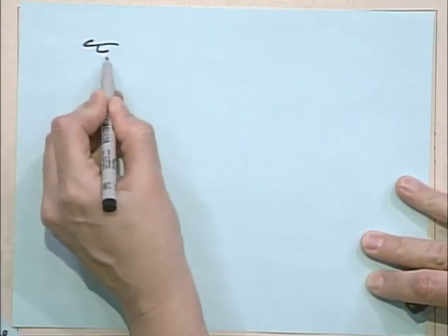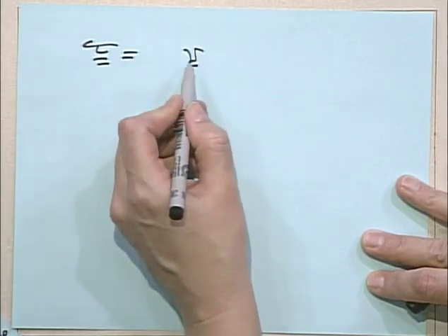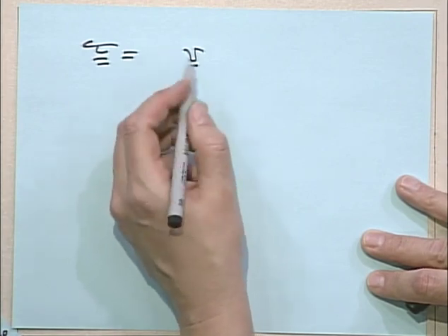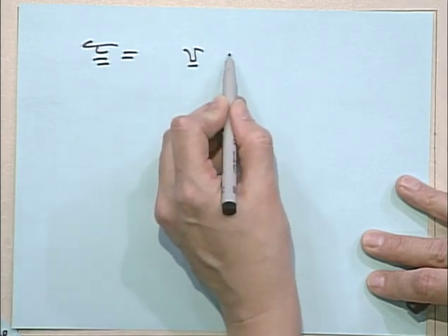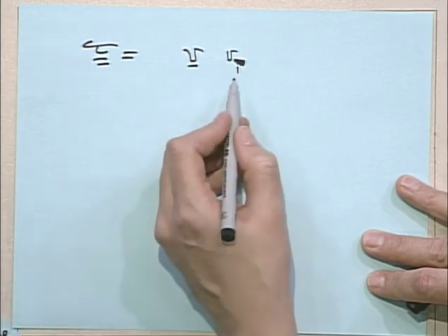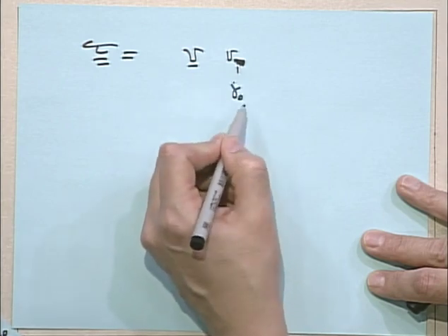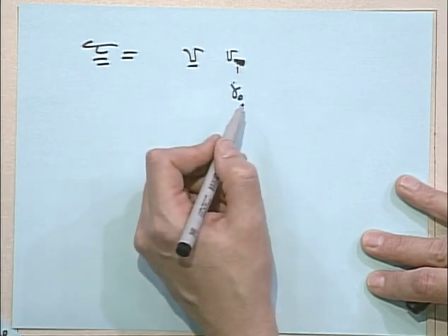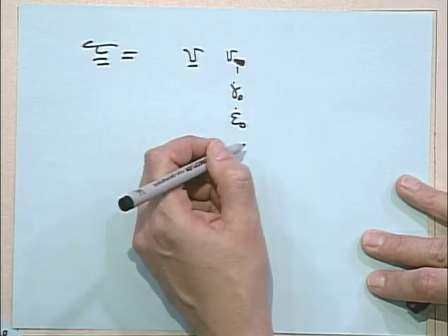If we make up constitutive equations, tau equals some interesting function, right? It's going to have v's in it somewhere. So maybe del v transpose, maybe some time integrals, maybe some other interesting things. It cannot have v2, v1 in it, for instance, because that refers to a specific flow. It cannot have gamma dot naught in it because that refers to shear flow. It cannot have epsilon dot naught in it. That's a parameter of elongational flow.